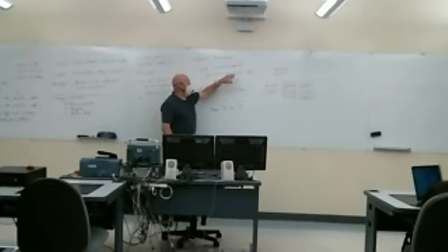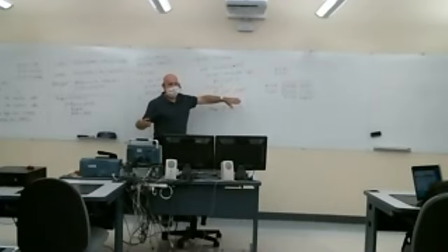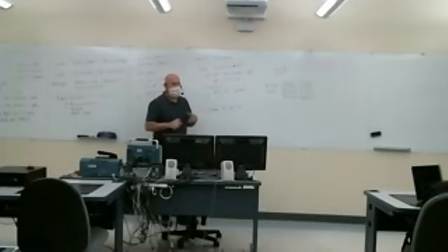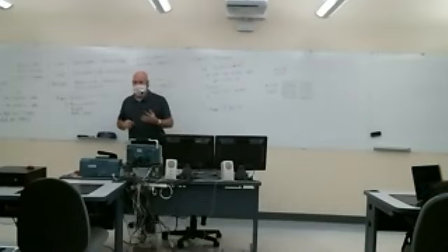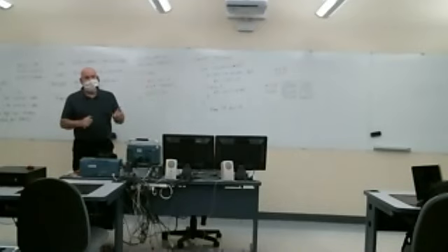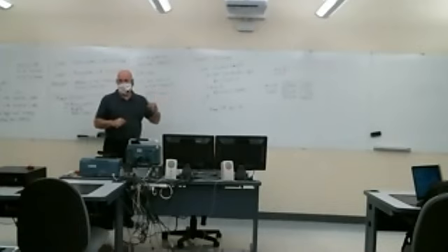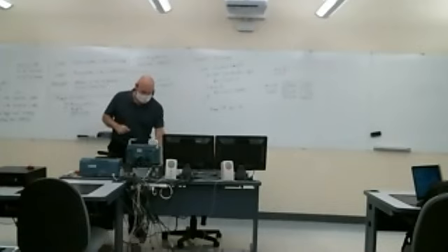If this pin is 1, I'm setting port 4 to 0xAA, which is 1010 1010, or whatever values you would use. So this ANDing operation, or masking operation, is pretty common when we're reading input pins. We want to determine whether one bit is 0 or 1.